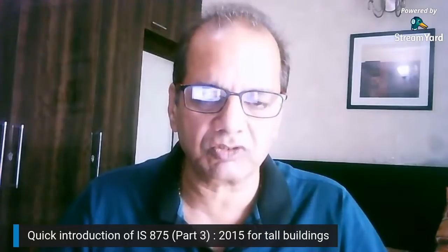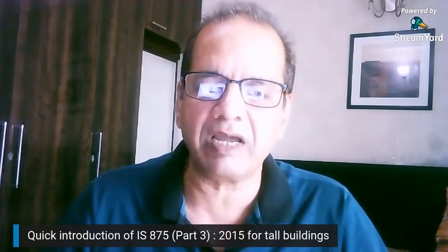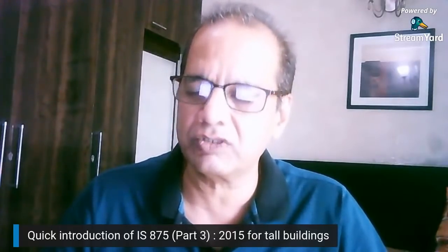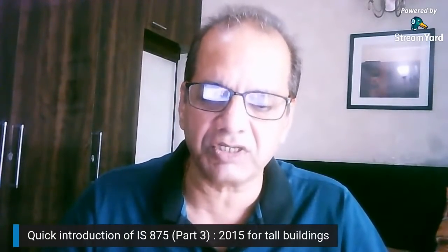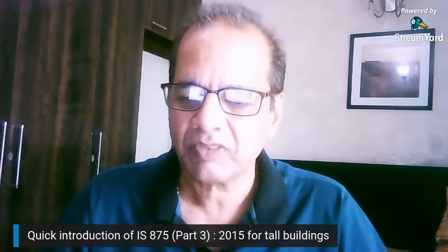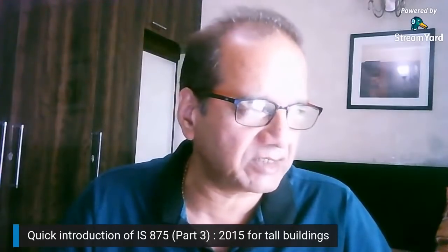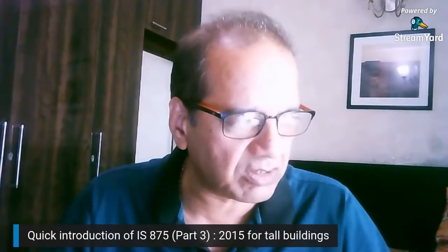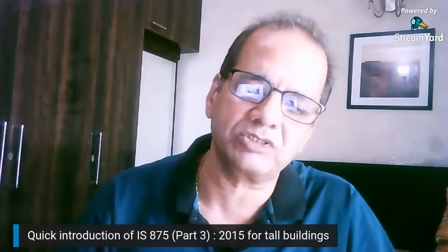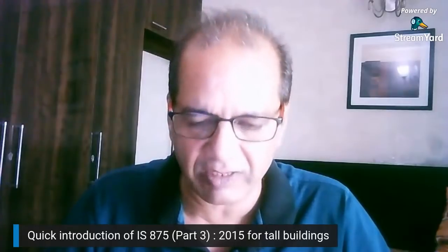Then comes the along wind response. For along wind response, Indian code has adopted the Gust Factor approach developed by Alan Garnett Davenport, one of the pioneers in the field of wind engineering. Though he is no more, we had the opportunity of meeting him in 1995 at the 9th International Conference on Wind Engineering in Delhi. He came there and we had an interaction also. So the method developed by Davenport in 1962 to 1967, that is called the Gust Factor approach, is still valid and is being used. Though some more approaches have been subsequently developed by Solari, Simiu and Scanlan, primarily the Gust Factor approach is widely accepted.